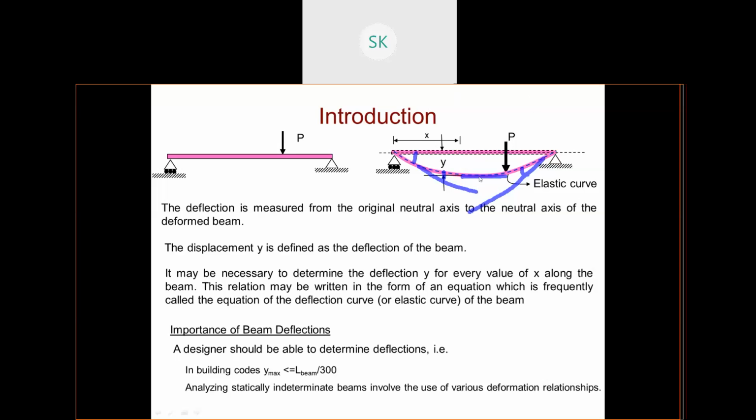Okay. So this is your theta, and this is your theta value, and this one is your deflection. See, deflection at this part is very less, right? Deflection at this part is the maximum. At the mid span, deflection is maximum and your slope will be 0.